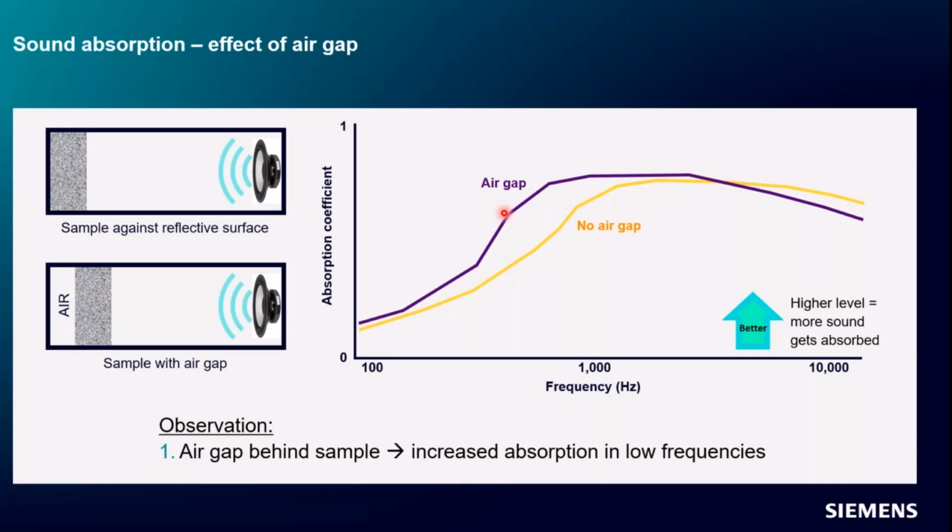Well, if you think about the mechanism that absorption works by, we said we're taking that pressure wave and we're actually deconstructing it and breaking it apart and turning it into friction, right? And so if you rub your hands together, the faster and the harder you rub them together, the more heat will get generated, right? It's a velocity-based thing to generate heat through friction.